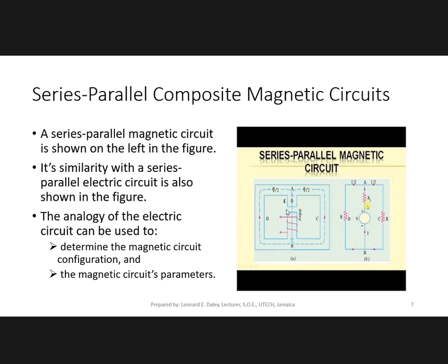Right. So the air gap is a reluctance. It offers very high magnetic resistance to the flow of flux, right? But this part of the magnetic circuit too, that the winding is around, also has a reluctance. So the total reluctance would be the reluctance of these magnetic parts here, the metallic parts, plus the air gap reluctance. Okay. Good.